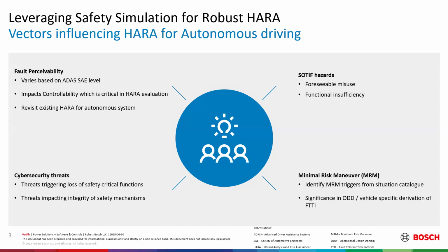And the last one is the minimal risk maneuver. We have to identify what the minimal risk maneuver is, what the triggers for it are, what the vehicle-specific thresholds, the safety thresholds, are, and the time available for reaction in the MRM.